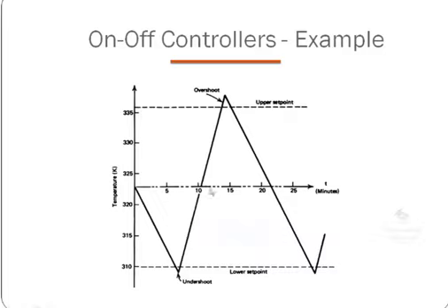Okay. Now, what is actually decided? 323 it has to be decided, right? Plus or minus 12 Kelvin is permitted, almost 12 Kelvin, not exactly 12. So 13 Kelvin they have decided, 310, and here it is 335. Within this swing, it is swinging. So when I am switching off the heater, what will happen? Per minute, 2 Kelvin will be reduced. So here I am standing, I am switching off the heater. Now the temperature slowly starts to decrease. It is coming to this point. And once it is beyond the acceptable limit, which means your neutral zone.